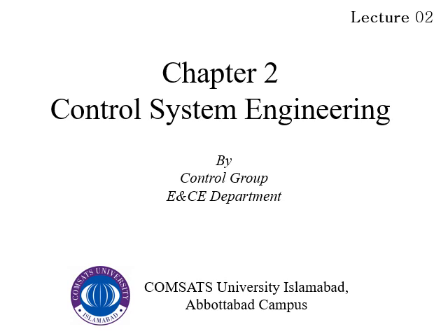Then we studied the configurations of control structure. The first is the open loop system and the second is the closed loop system. The basic difference between open loop and closed loop is the feedback path. In open loop systems, we don't have a feedback path and have a predefined input-output relation.